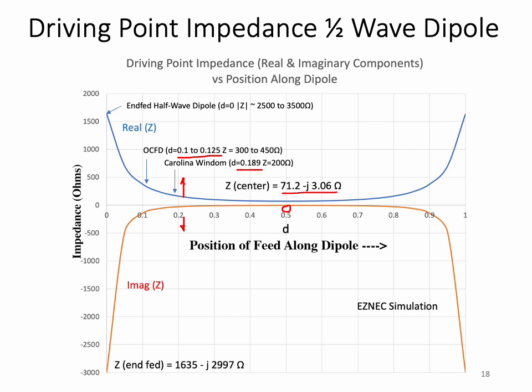Finally, when we drive the antenna from its end, right here at the 0, we see that the impedance effectively skyrockets to values in the 2500 to 3500 ohm range. End-fed half-wave dipoles are another form of multiband antenna, which typically use 49-to-1 or 64-to-1 transformers to match the 50 ohm coax to these very high impedances.